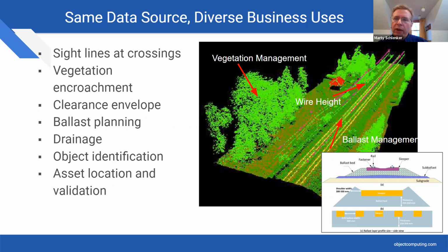And so when a wire was installed above the track, there may have been plenty of clearance, but very gradual swaying in the pole and its foundation, that may have happened because of seismic events or settlement of the ground in which the foundation sits, will cause the wire to sag. And so if the sag puts the wire close to the top of the height of railroad equipment, then you would want to know that. And you could send out a separate survey, but if your railroad regularly takes LIDAR, that would probably be the most frequent and effective way to accomplish that.